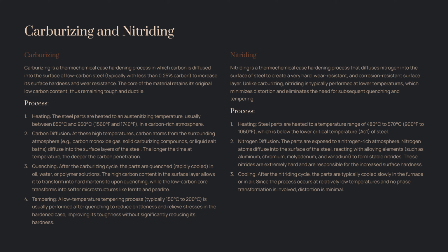Rinsing. The parts are then thoroughly rinsed to remove any residual cyanide salts. Tempering. Optional. A low temperature tempering may be performed to improve the toughness of the case and relieve stresses. Advantages of cyaniding. Rapid case formation. Cyaniding is generally faster than carburizing for achieving a given case depth.